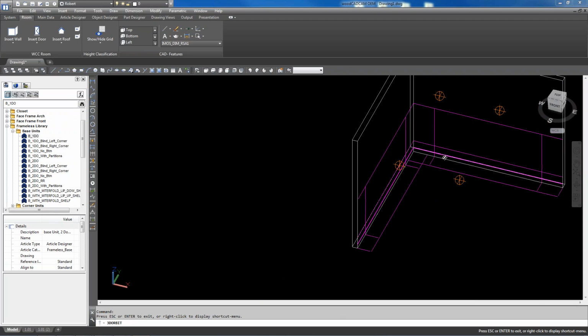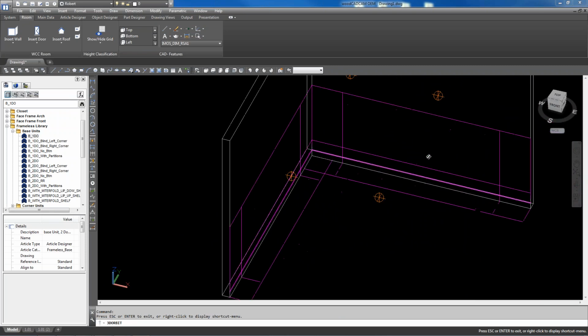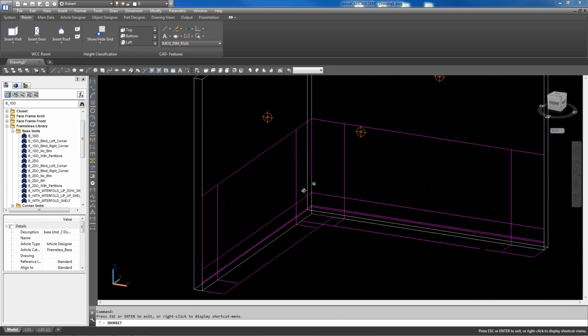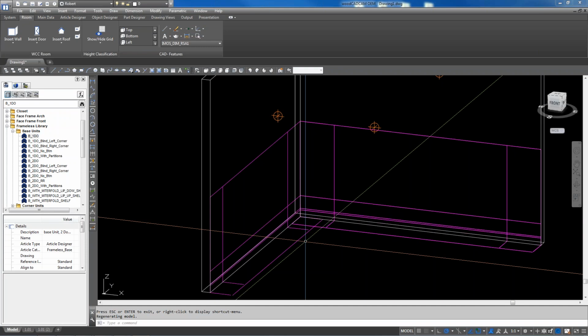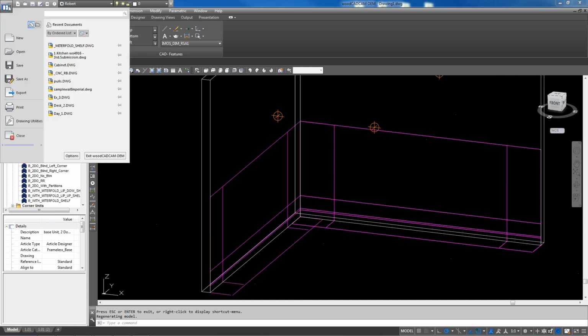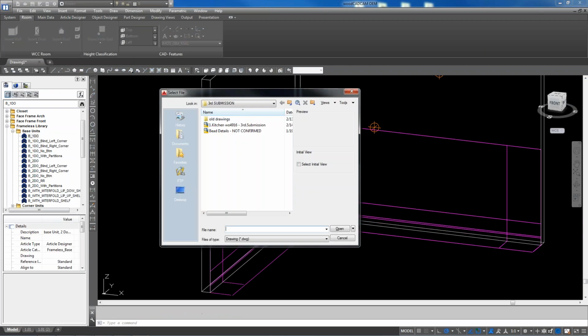Once we set up this grid, is it going to stay, or with every drawing that we start will we have to set up a new grid? Oh, well, no. You can save the default grid, but you have to save it in your template. We'd have to change it in your template. Okay. Shall we do that? Yep, we can do that. But get it to work first.